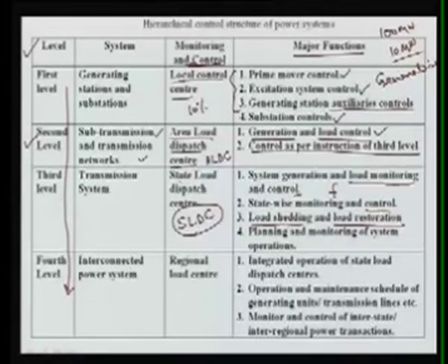If some part of the system or the complete system is in blackout, then you have to restore the system, and that policy is decided by the SLDC itself in that state. They plan some restorative plans, and based on that we keep on connecting the various elements of the power system, so that we can provide electricity in much less time.